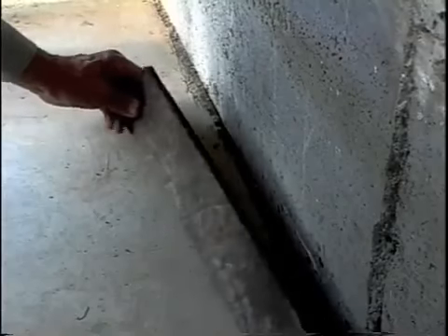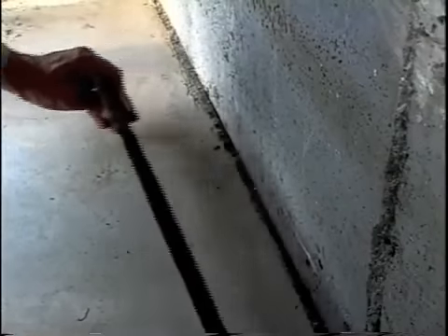When the clay gains moisture, it swells and easily lifts concrete slabs. For this reason, the slabs should be floating or independent of building foundations. I'm talking about such slabs as walkways, patios, and garage slabs. Place isolation joint material between the slab and the building. The joint material is usually 1/2 inch thick fiberboard. Make sure the fiberboard goes all the way through the thickness of the slab.